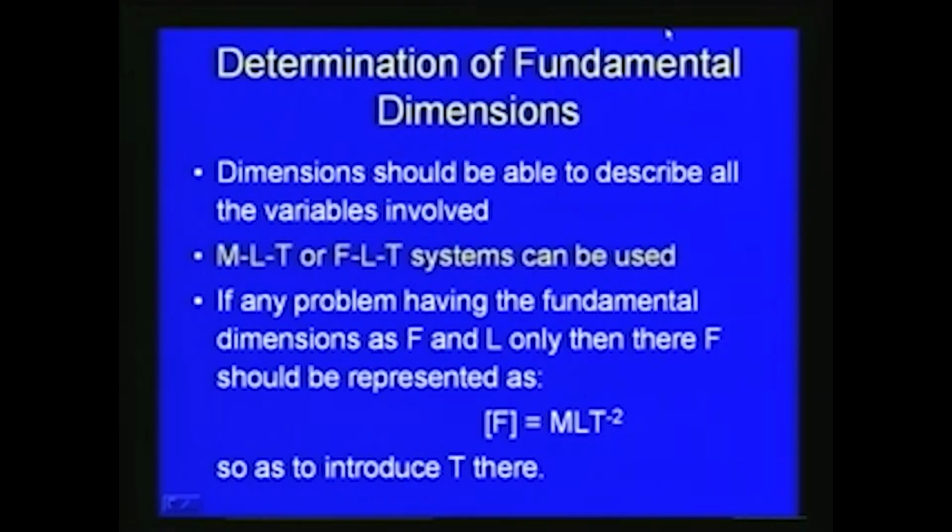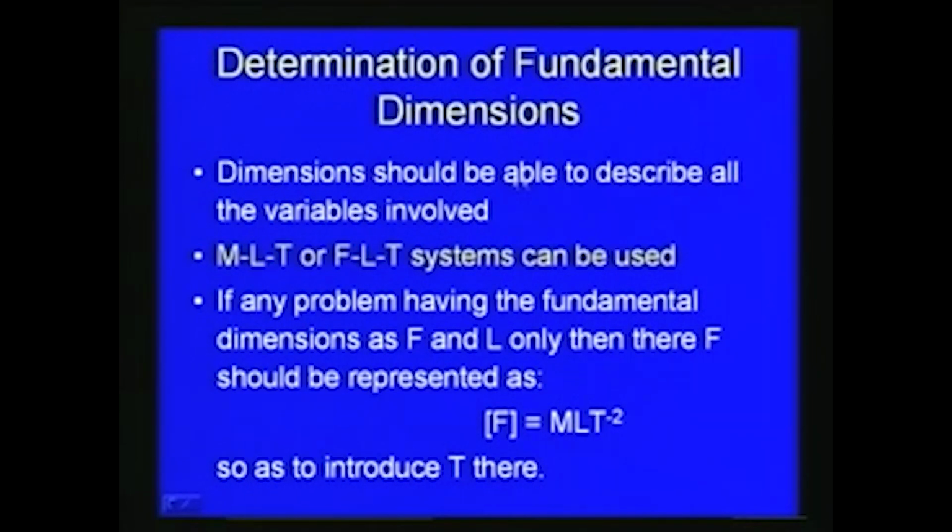And then the other important point is that we have to decide the fundamental dimensions which we will be using. In the Buckingham pi theorem methodology, the dimensions should be able to describe all the variables involved, either M, L, T (mass, length, time) or F, L, T (force, length, time) systems can be used. So depending upon the case, we can use the MLT or FLT system.